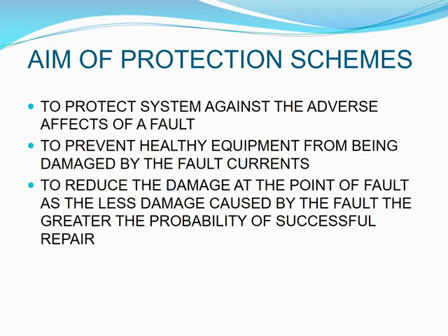So we need to isolate the cable as soon as possible so that the damage on the actual cable becomes minimal and it only is really on the faulty portion of the cable. This will then make sure that we are able to repair the fault at a faster rate.